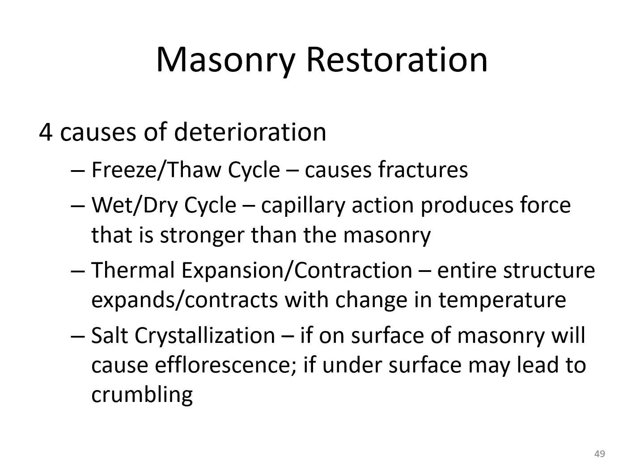So what about masonry restoration? Well, we have four different reasons for deterioration. I spoke about it a little earlier, the freeze-thaw cycle, which causes fractures. Also a wet-dry cycle. That's another problem. That's why you don't let CMU units dry out too quickly. They tend to crack. That's why the temperature control and the moisture control is made. But going through that cycle, as the wall is exposed every day outdoors, causes the cracking problem over time. Then you have thermal expansion and contraction, because even though stone or bricks expand and contract and change with temperature, not as much as wood or metal, they do. Salt crystallization, that's the efflorescence. So those are the common problems that you may encounter.